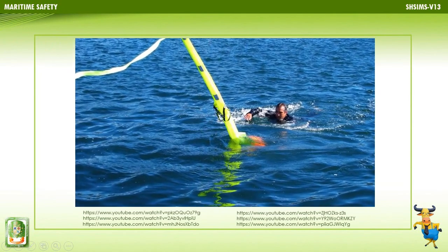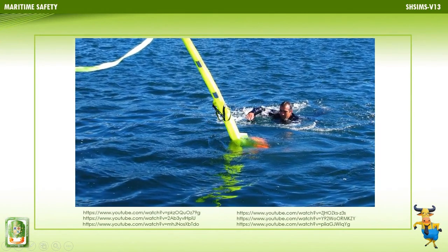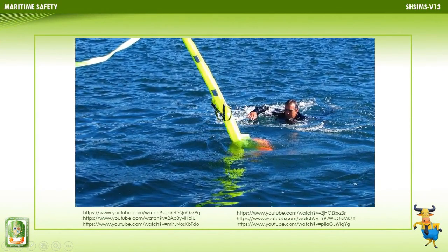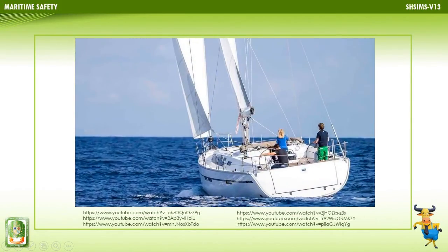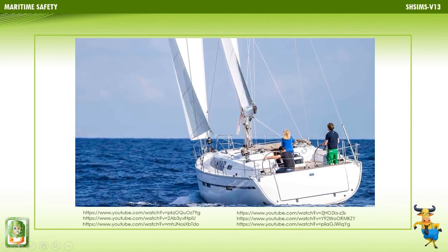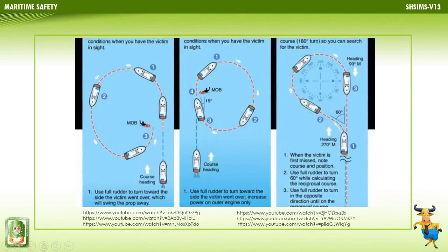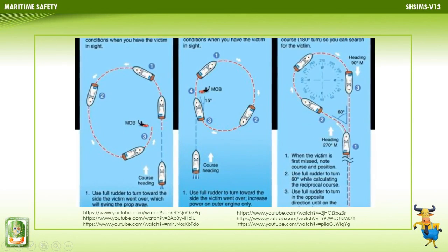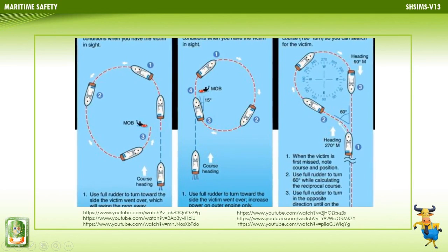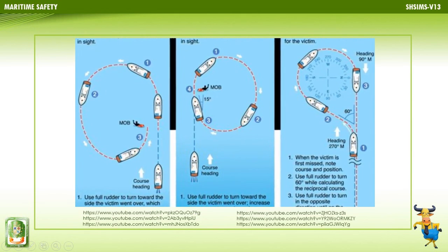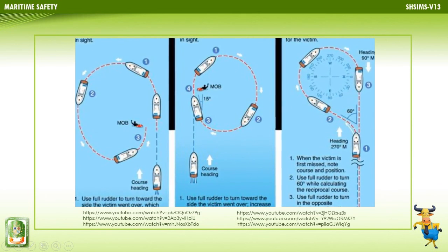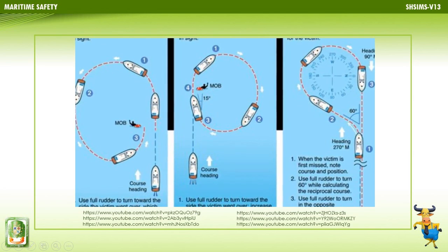While simpler than a Williamson turn, this method depends heavily on the wake, or floating datum, being visible. Both may be rapidly lost from sight in bad weather, especially at night or in poor visibility. The size of the turning circle will determine at which point the vessel returns to cross its original water track. With a large turning circle, there is a small but potential risk of running over the floating datum or even the man overboard if reference to either is lost during the turn.